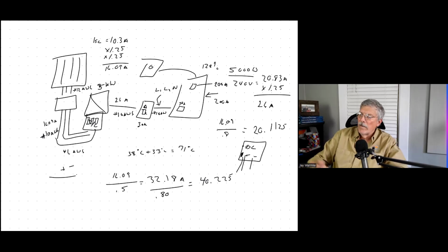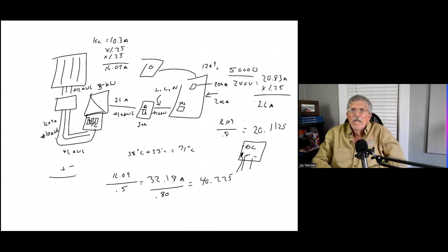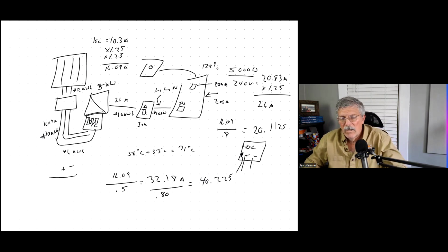So the 3-line drawing is going to show you all the connection points in much more detail. The 1-line drawing just gives you a sense of the architecture of the system, but it's not showing you all the wires. When you submit plans to the authority having jurisdiction, which would be your code enforcement office or whoever's giving you your permits, they're always going to want to see a 1-line drawing. They want to see something that tells them what this thing looks like, and they'll already know that you're not showing them all the wires.